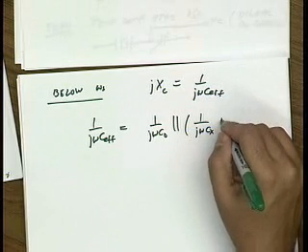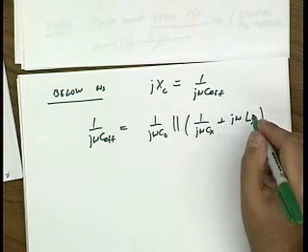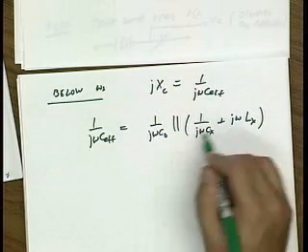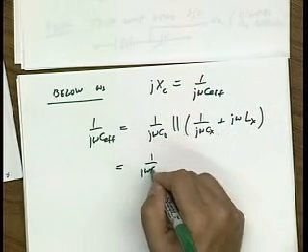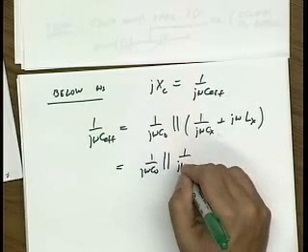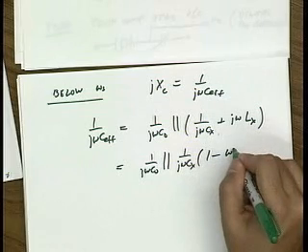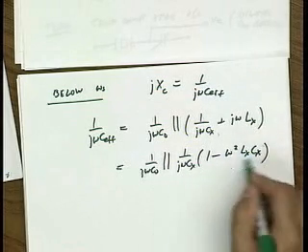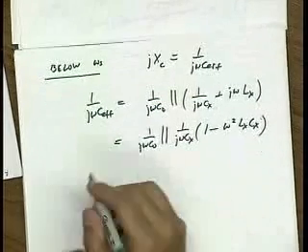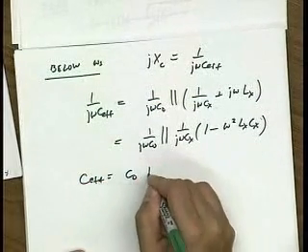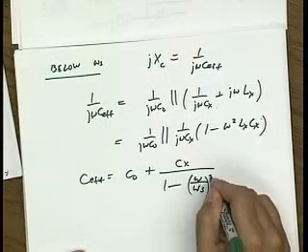So we have our crystal, and we're forgetting about the Rx for now. Let's just simplify it. So these are in series, and then they're in parallel with Cx. Well, because I'm below resonance, I can factor this term out, and I get 1 minus omega squared Lx Cx. This term is positive, so this looks like 2 capacitors in parallel, so that C effective is C naught plus Cx divided by 1 minus omega over omega s squared.